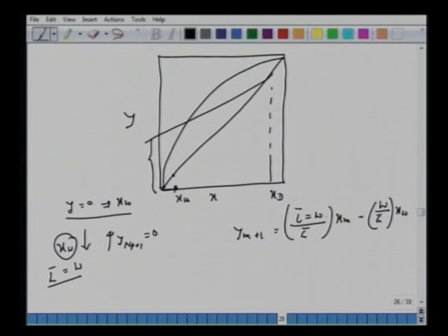So now with this slope, or with the negative intercept, you have to connect like this. This will now correspond to your xf or the q line. So notice the difference here. Instead of connecting from here, now you have connected with this x-axis where y equal to 0, because this is what the operating line connects. The two phases, the vapor which arrives here and the liquid which leaves here, the operating line connects like this.